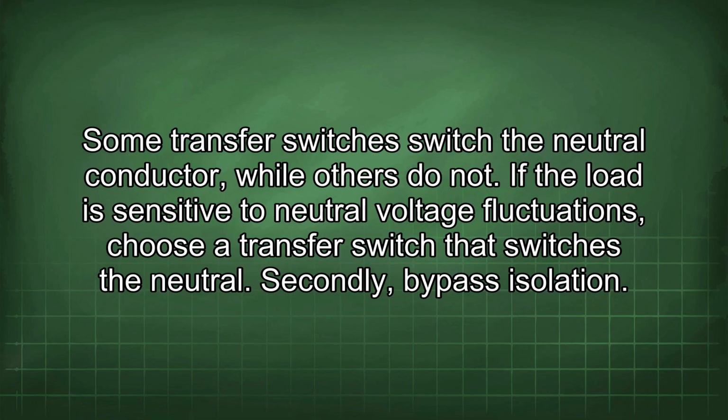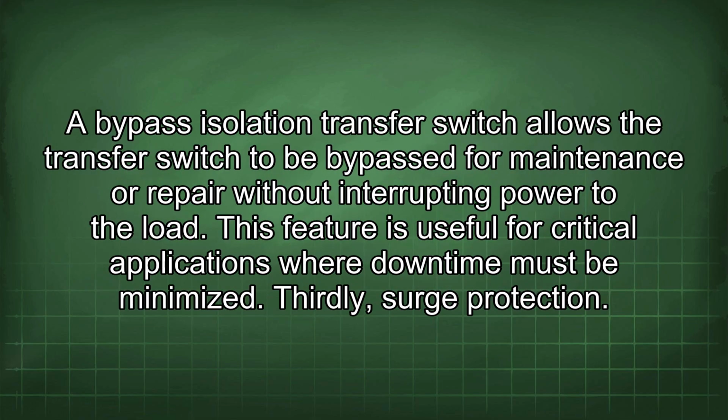Secondly, bypass isolation. A bypass isolation transfer switch allows the transfer switch to be bypassed for maintenance or repair without interrupting power to the load. This feature is useful for critical applications where downtime must be minimized.